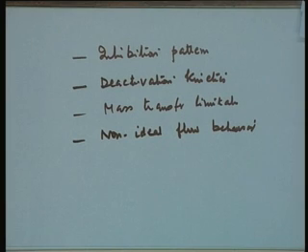In many cases, practical reactors may not be an ideal CSTR or an ideal PFR. There might be some deviations from ideality because of the packing characteristics or some channeling taking place. In the laboratory you can easily maintain a good plug flow reactor, but in a large scale system it is always difficult, and it is desirable to characterize your reactor with reference to flow behavior and then apply a correction factor when the design part comes in.